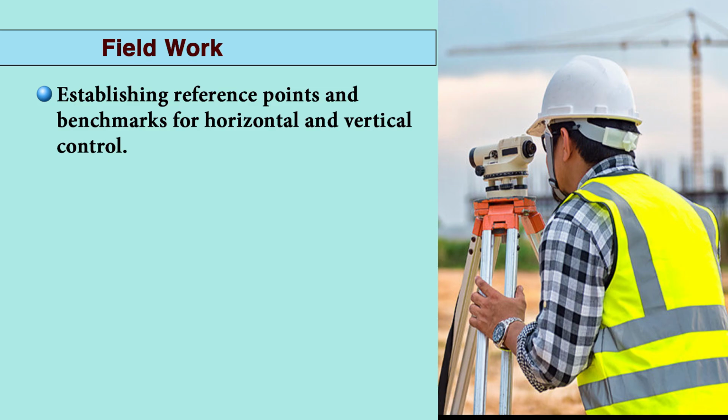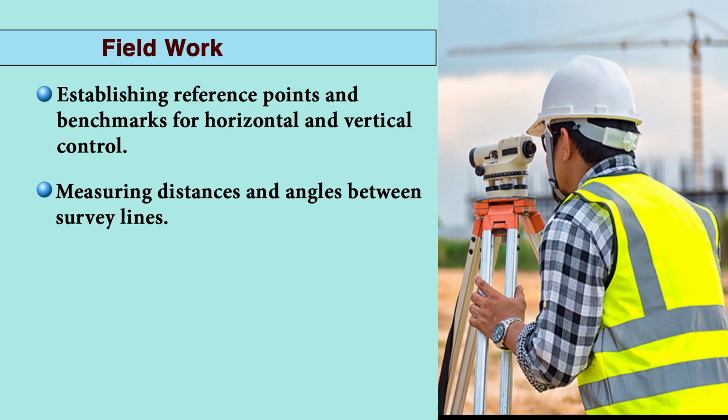Because when we do the survey work, we have to establish some benchmark and we have to establish these benchmark frequently, because during the surveying work, we will be going through a long stretch. So, we cannot all the time rely on the benchmark which we have established earlier. So, we have to keep on updating the benchmark, means after a certain surveying work we have to establish a new temporary benchmark, so that our accuracy of the surveying can be ensured.